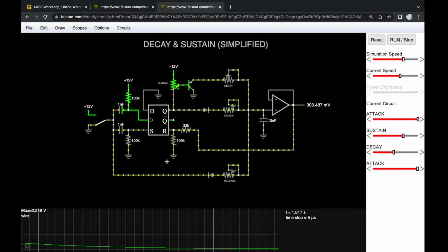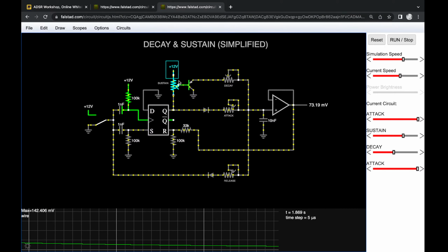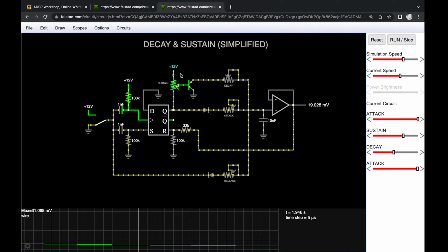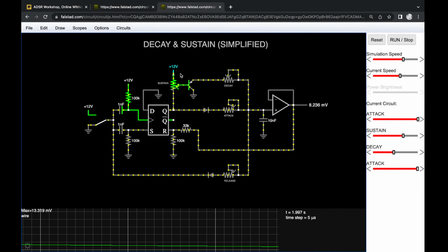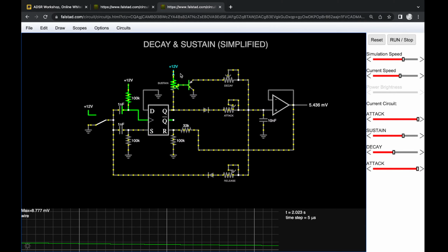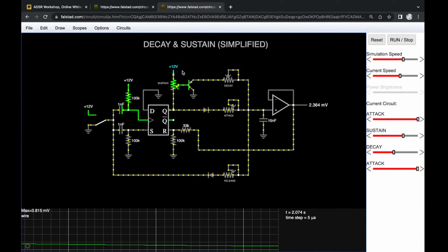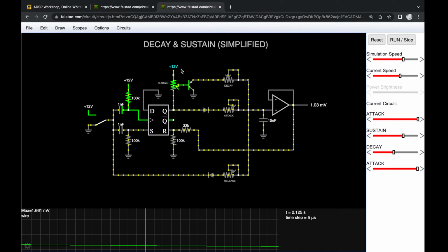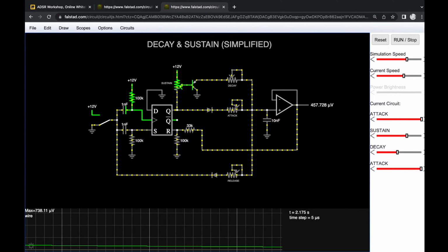That's it. One thing I just noticed is someone mentioned in the chat that we don't use the full range of this, and it's still true because the peak value of our envelope is now 8 volts, but the sustain can go up to 12 volts. So that means there is going to be a significant dead zone in the potentiometer. Off the top of my head, I don't have a really good solution for this right now because specifically getting 8 volts here is going to be a bit of a pain. So I think I'm going to be okay with the dead zone for now. Maybe for the proper video release, I'm going to have a good solution here. But maybe someone in the chat has an idea.